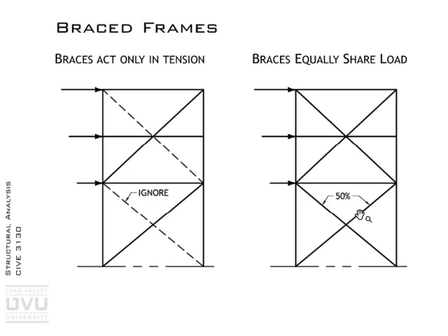And again, a way to quickly in a model say, okay, well, if I have a story force of 100 kips, and that's going into two brace frames, and I have two compression or two braces that'll share the load. So I take 100 kips, split it in half to each frame, and then half again into the brace.